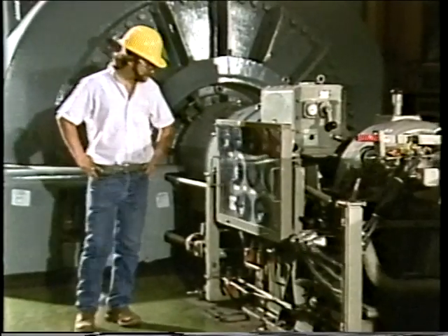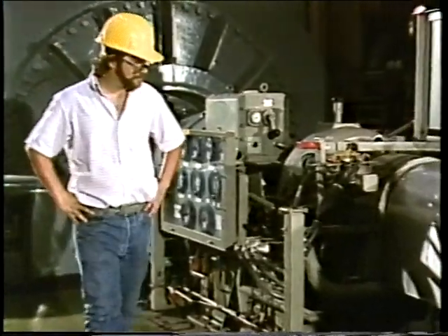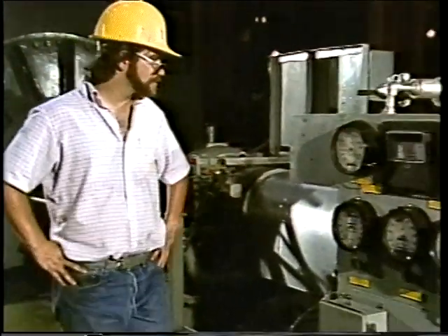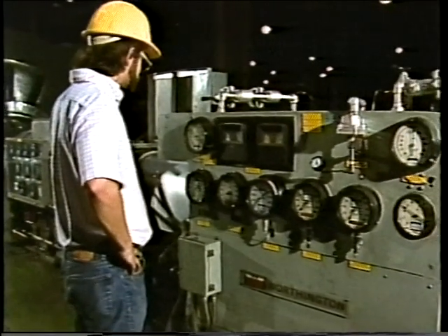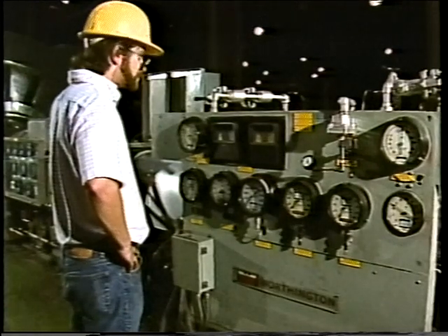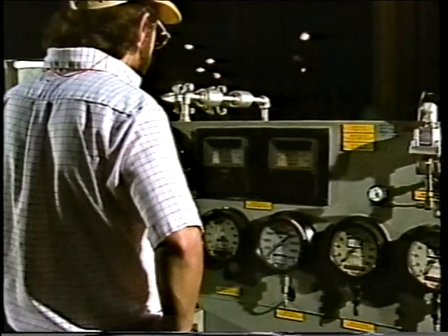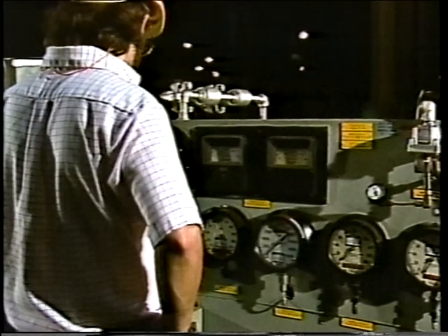But to really understand what you're doing when you use a strobe light, you'll have to have some specialized training and practice. Now, another thing that must be checked and matched against the baseline data is equipment load. Equipment load is basically the amount of work that's being done by the machine being monitored. Equipment load is normally checked by looking at meters or gauges connected to the machine. These may be flow rate gauges, discharge pressure gauges, or ammeters.